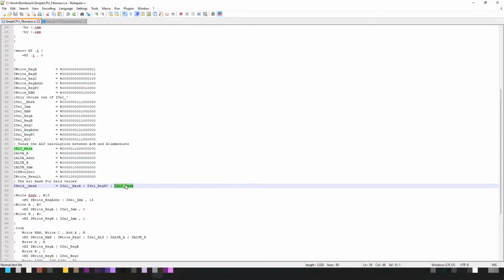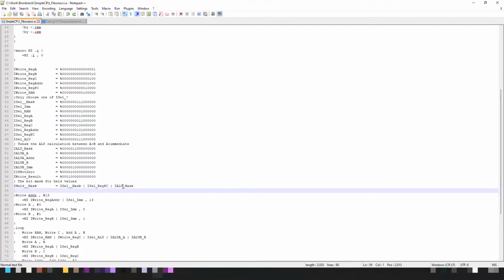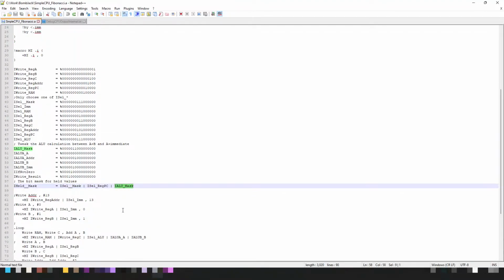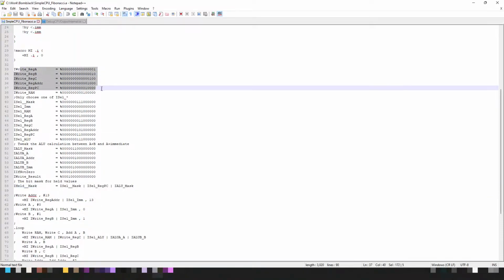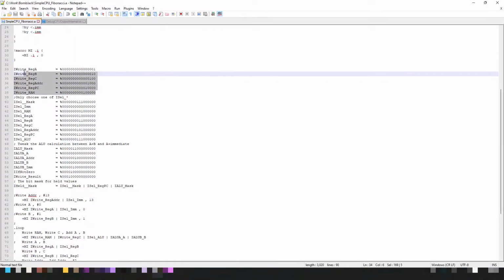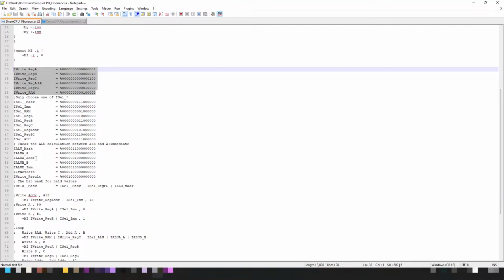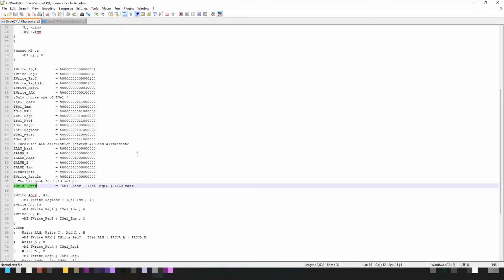It doesn't quite operate the same as a latch, which is slightly annoying, but that's what the counters do. And I also want to maintain or hold the state of which inputs I'm selecting for the ALU inputs, the input A and the input B, so I want to hold those for longer. All of the other signals to do with writing or loading values, I want to have as an edge. That's why I don't have those as part of the held mask.